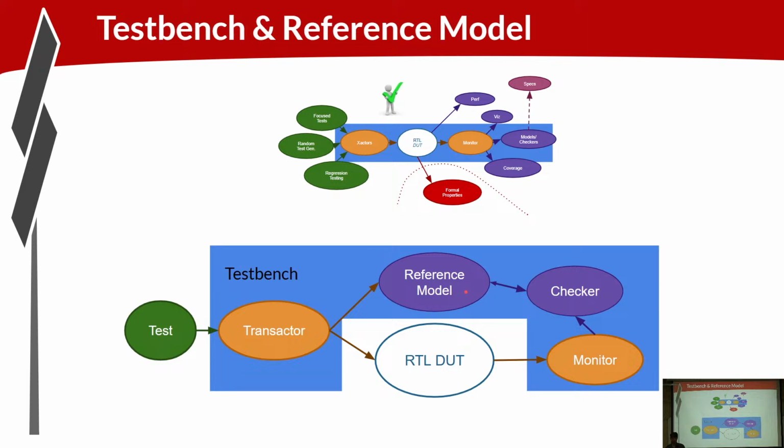So it should be fine for either choice from a functional correctness perspective, but maybe the reference model has an easier time doing its job if it knows the choice that the RTL made. So as long as you're careful about it, it's okay to feed back that sort of information from the RTL to update your reference model and simplify things potentially. So you might have a little bit of connection in this direction as well.